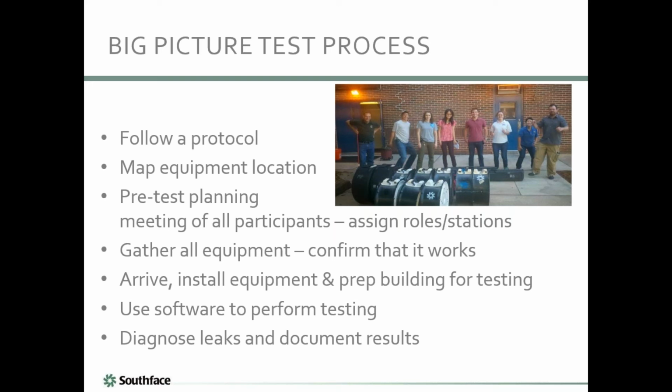And I think we have the numbers for this building coming up later on, but if I remember right, it was over 60,000 CFM 75, and like I said, I don't think we had enough capacity. We were able to plot the curve, but after we retested it, it dropped to less than 40,000. So it was very valuable.